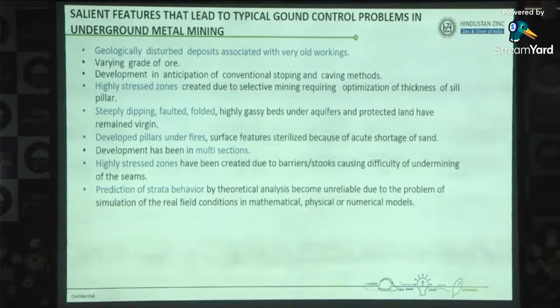Recalibration is one of the must-required things for a model. Suppose you are doing modeling and you are expecting a hanging wall deformation of up to 2 meters. If you have installed an MPBX in the hanging wall and we are getting the exact same numbers of deformation, then we can say that the data we have taken in the design is right.